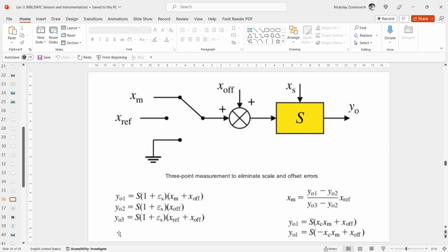An alternative way to reduce offset is flipping the directivity of the sensor without changing the sign and value of the offset. So clearly, the method can only be applied for sensors that are sensitive to the direction of the input quantity, which should be a vector, right?